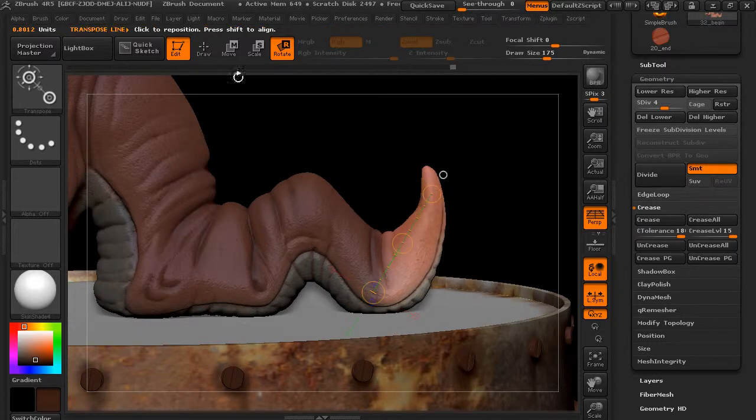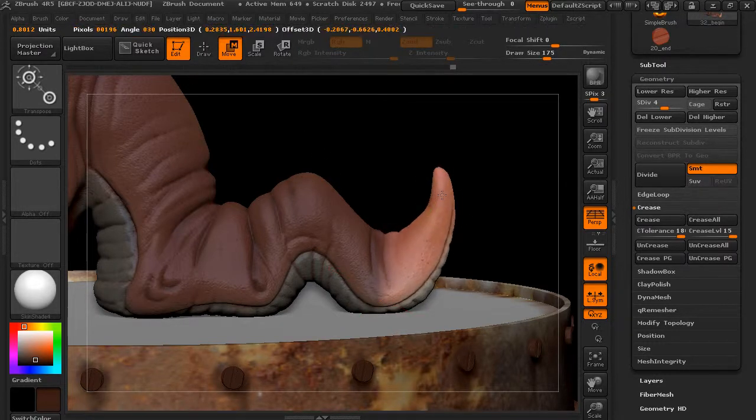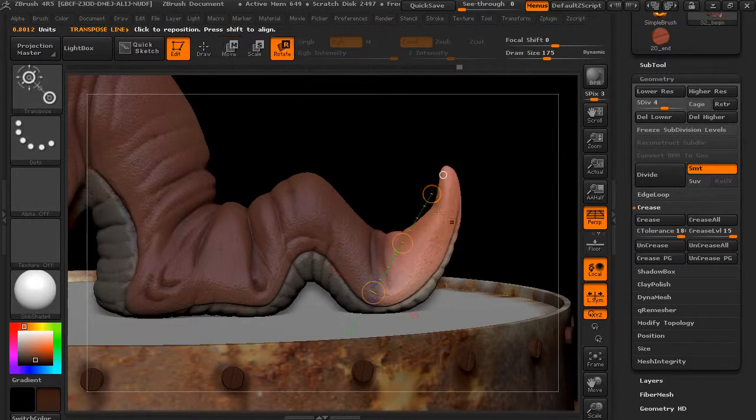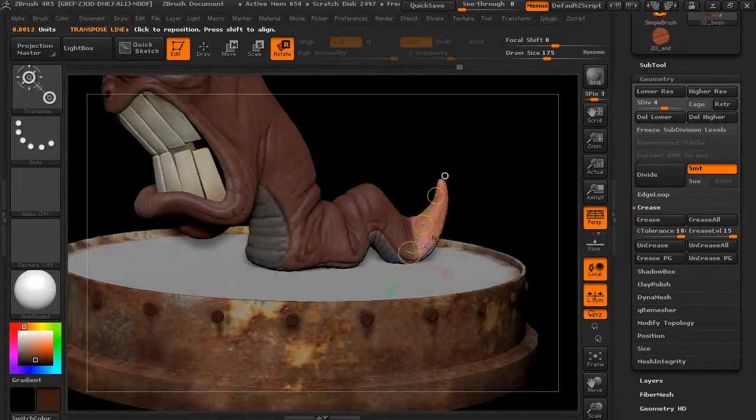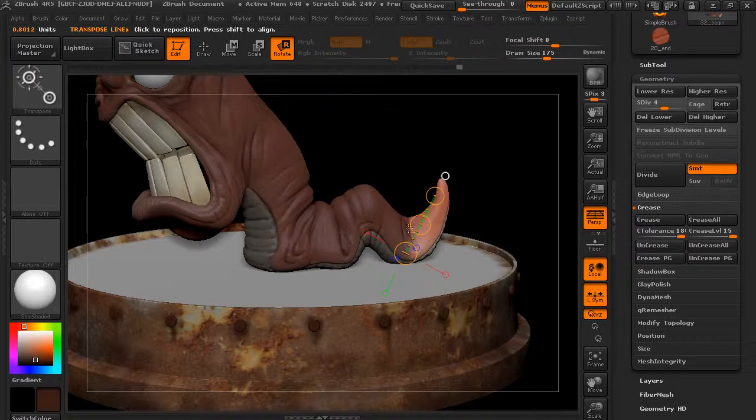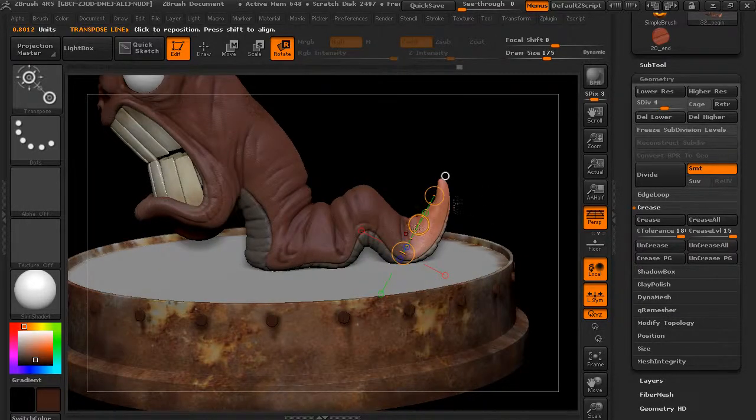Now if we want to distort it, we can choose move instead of rotate, and then we can move it wherever we want. Okay, rotation will help keep its size and the shape that we want it to have. So if you have an arm or something, control drag down the arm to create that topological mask, and then create your transpose line. It's sort of a temporary joint to pose it. Then you could move down and pose the elbow and so forth.